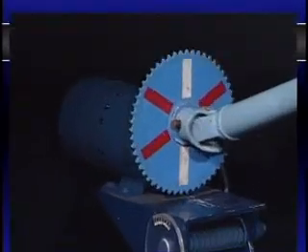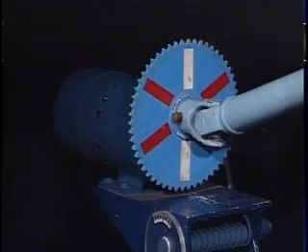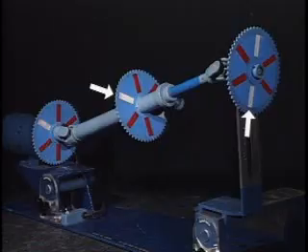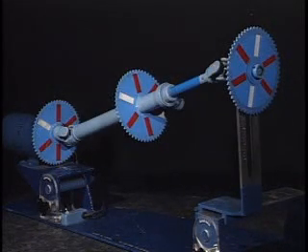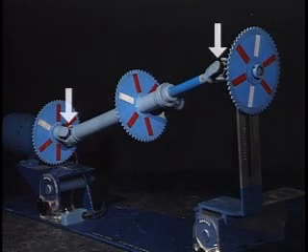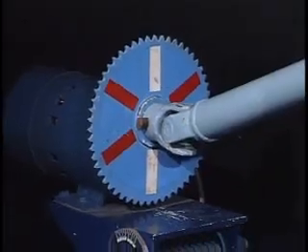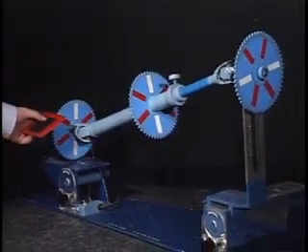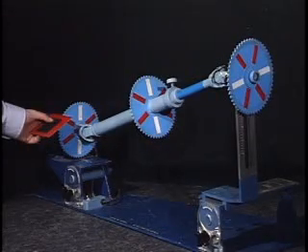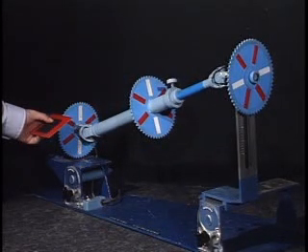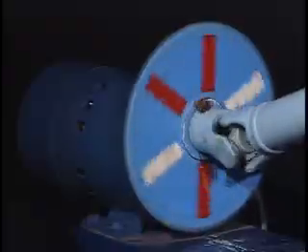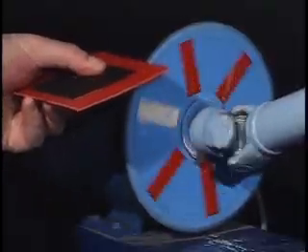This model has an electric motor which rotates at a constant speed. As you can see from the white stripes, we've adjusted the yokes so that they're 90 degrees out of phase. When you look at the driveline model, you can see that the yokes are at right angles. Each shaft has a sprocket attached. When the driveline rotates, a card can be held next to the sprocket, and the sound will indicate variations in speed. For example, the first shaft from the motor rotates at a constant speed and sounds like this.